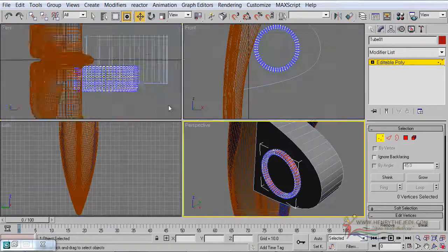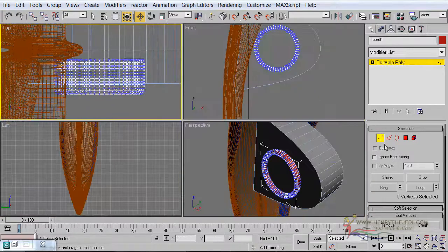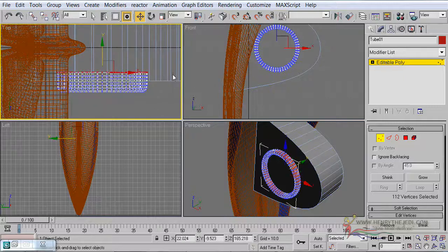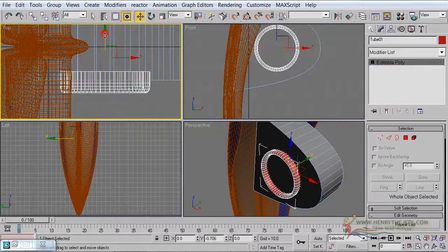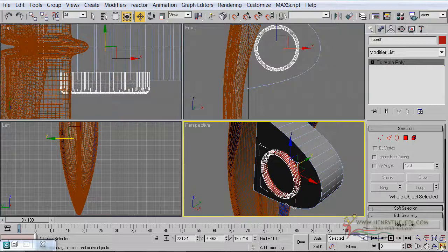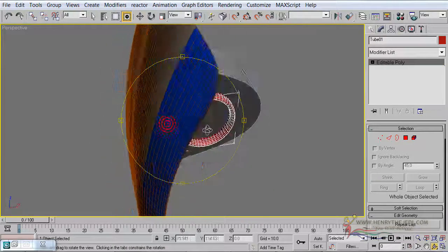Then we're going to be clever because we don't need some additional unnecessary vertices. So the best way, of course, is to get rid of them. Select the vertices mode, and then select each of these vertices there on the inside and simply delete them, so that it frees our computer from unnecessary polygons. And those can simply be dragged backwards. The whole idea is that these things are hidden within another structure. So what's the point of rendering or leaving them with so many vertices while nobody will hardly get to see them anyways? So you see now what we have.